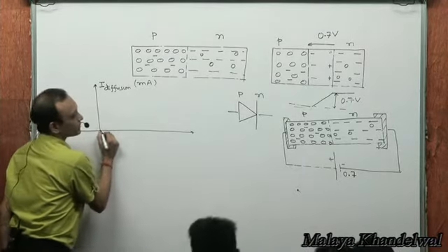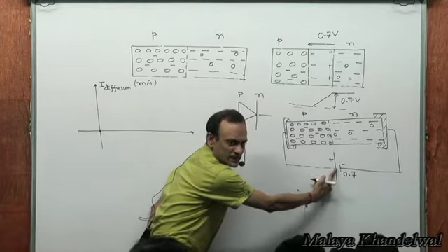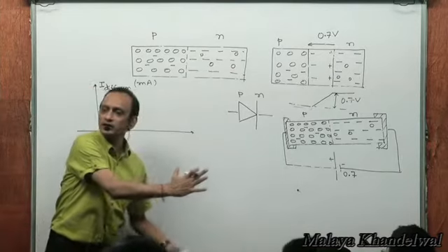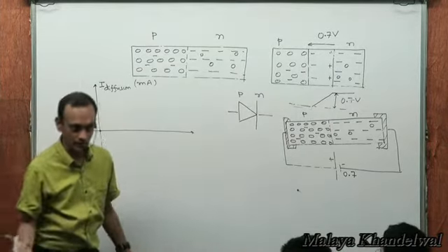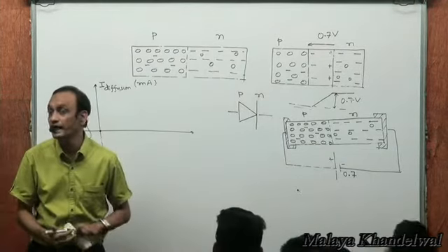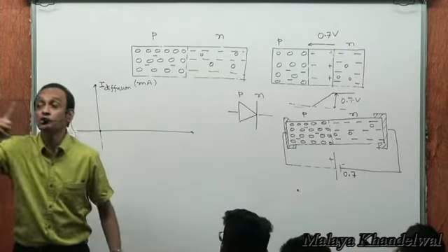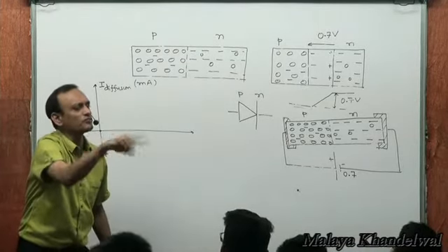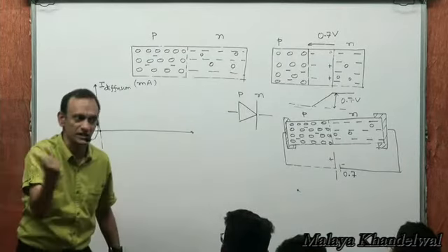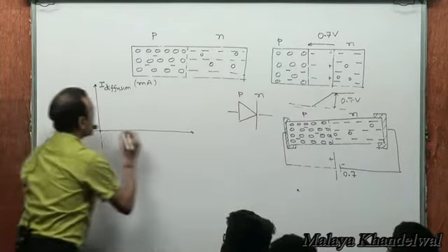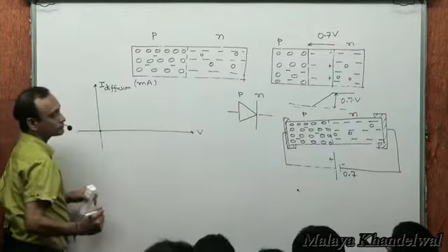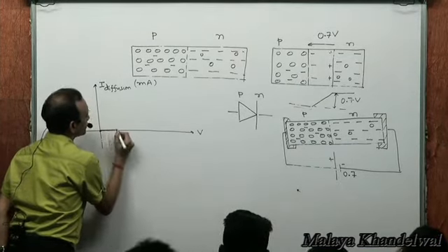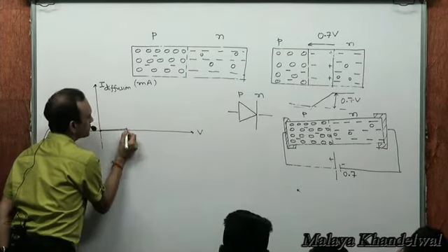What really happens is, when I used a rheostat, when the voltage here was 0, the depletion layer was fat and bulky, and it prevented migration, diffusion of holes and electrons on either side. Majority charge carriers, what does the depletion layer do? The depletion layer prevents diffusion of majority charge carriers, but it can enable small amounts of current of minority charge carriers, which is a drift current, right? So essentially, current is very minimalistic,